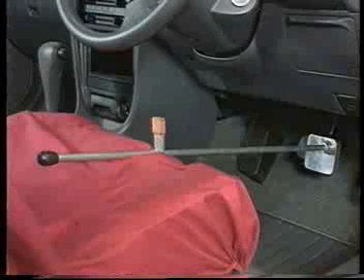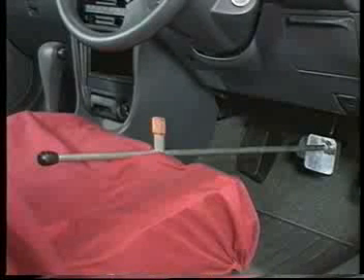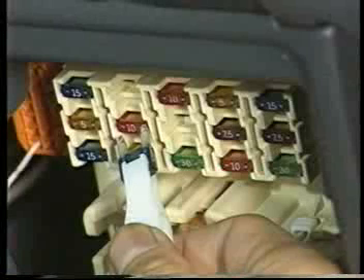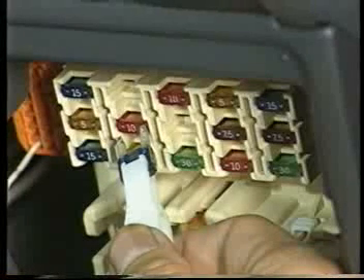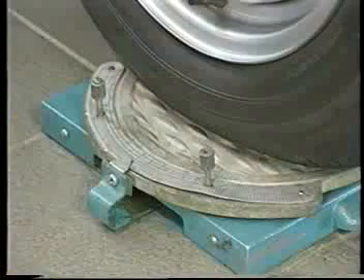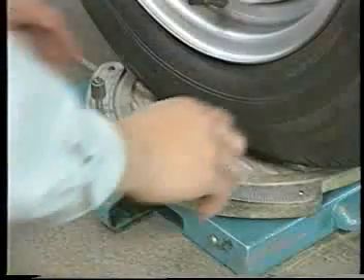The inspection should be carried out with the vehicle empty and the front wheels locked, so depress the foot brake using a brake pedal pusher. To prevent the battery from discharging while you are doing this, remove the brake light fuse so that the brake lights will not light. Then release the turning radius gauge lock.